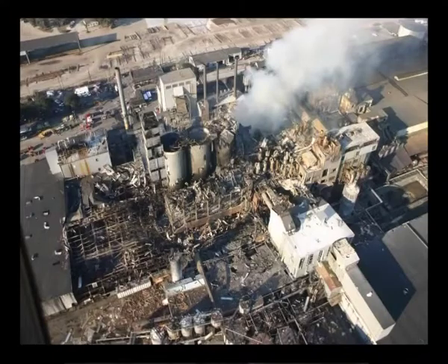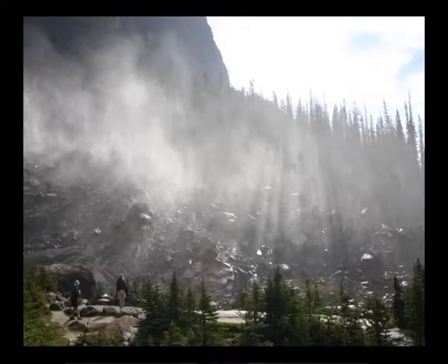gas. In burning such high moisture waste, primary chamber burners are needed to ensure complete oxidation of combustible solids and vapors for the elimination of smoke and odors. Confident smoke and odor control requires auxiliary fuel burners under automatic temperature control in a secondary combustion chamber.